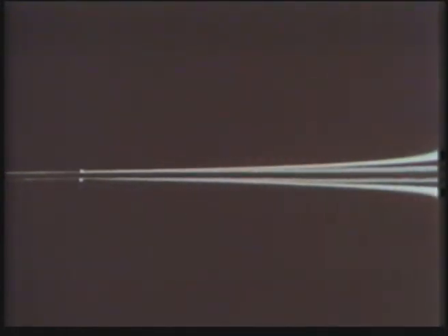Here's the normal flow. We will speed up the flow. Now, the flow velocity outside the boundary layer has increased. At any position along the plate, the boundary layer thickness is now less than before, because with a higher mainstream velocity, the boundary layer has had less time to grow.